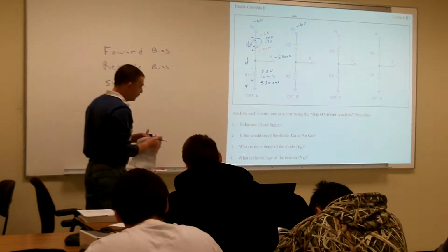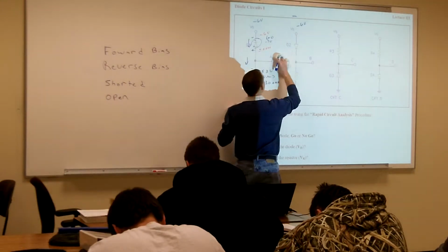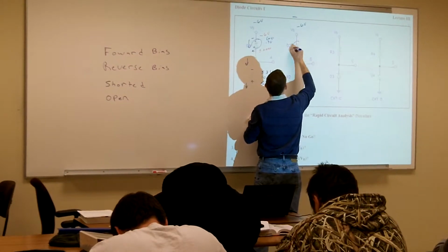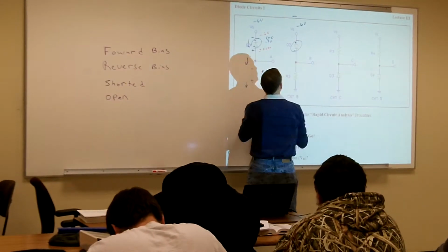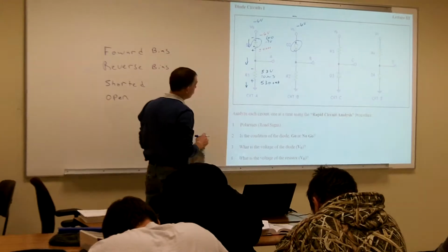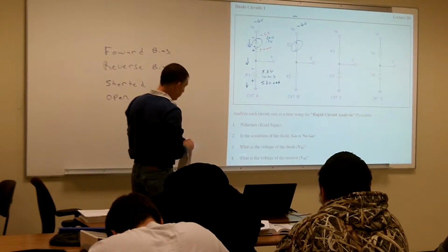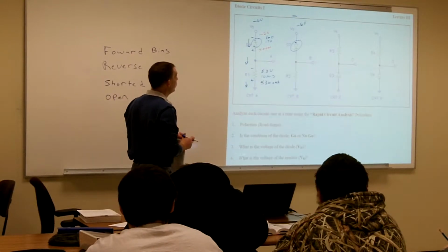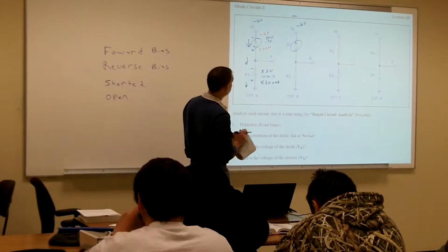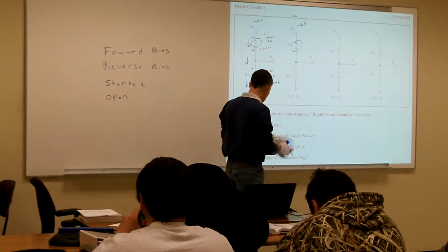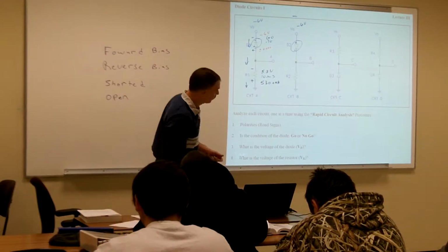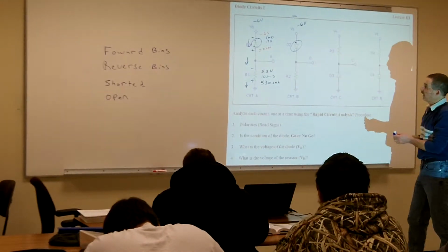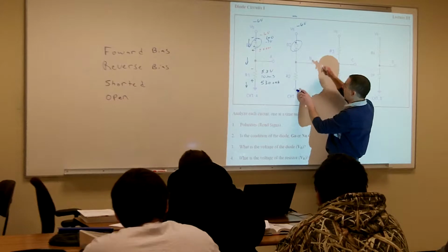All right, let's see my first step. Circle your active component. And then put your polarities inside there. Okay, then what's my next step? Treat it like an open. Treat that diode as an open, and then we're going to bring, what did I call those? Soft voltages. Good. So we're going to bring down my soft voltages as I treat that diode as an open.